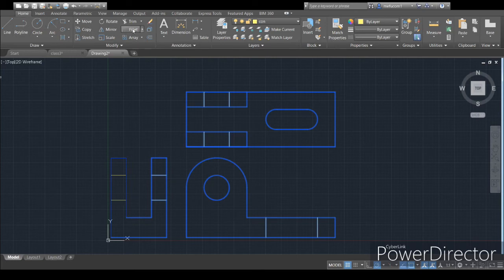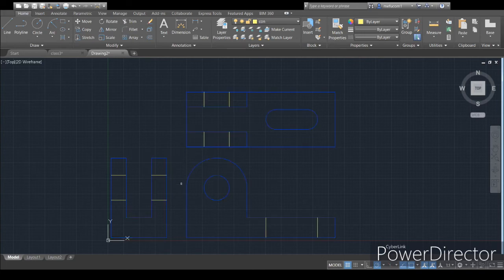So we go to fillet. Go to the proper ones. You want to go right here. You want to go down to radius. Click on radius, hit 3, enter, then you choose the other portion that you're doing, and then you hit fillet again. Come back right here.